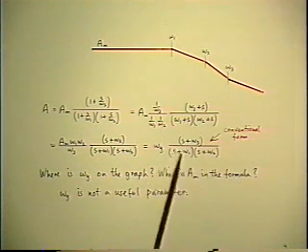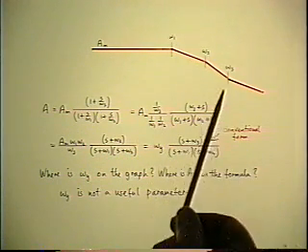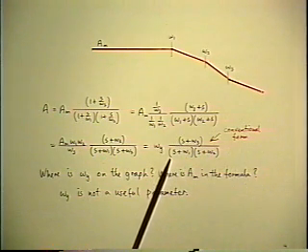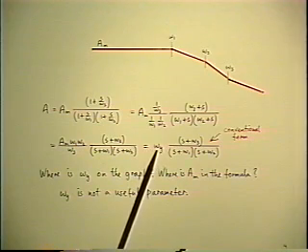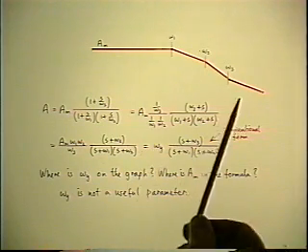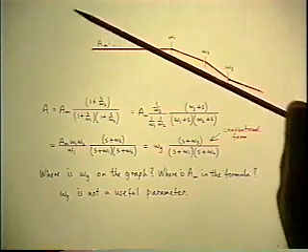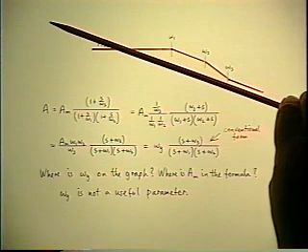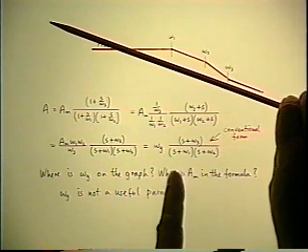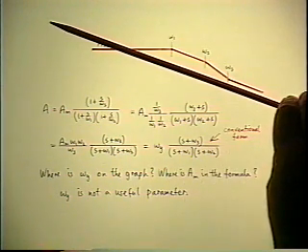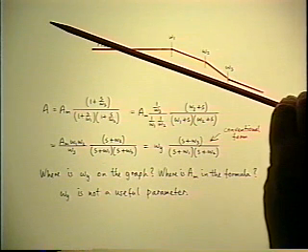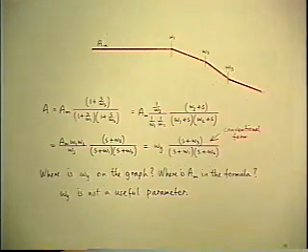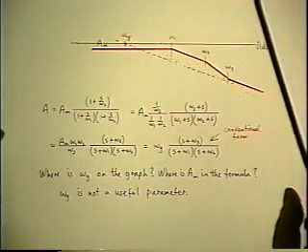To make this factor independent of the three corners, you have to let s go to infinity. That leaves you with a 1 over s, which is why the coefficient in front is a frequency. So the infinite frequency asymptote, this one, is omega y over s, where the rest of the term has gone to 1 at infinite frequency. And so directly from that, omega y is the frequency where the infinite frequency asymptote crosses 0 dB.